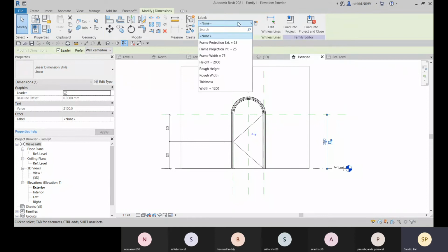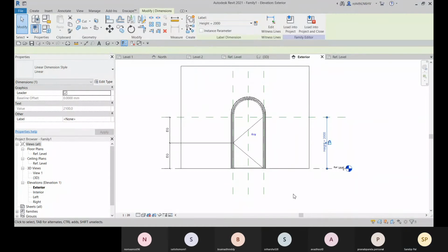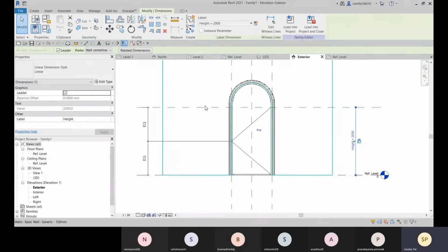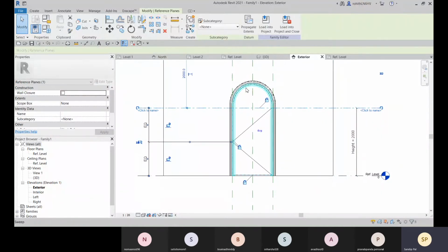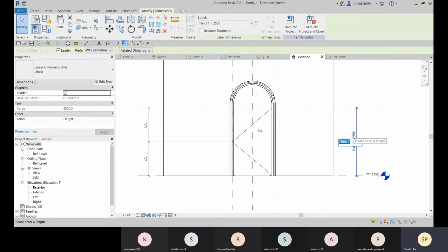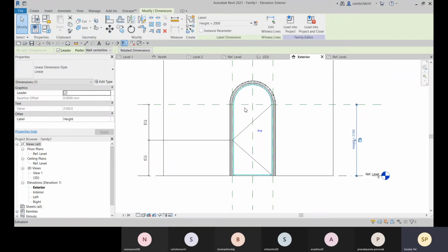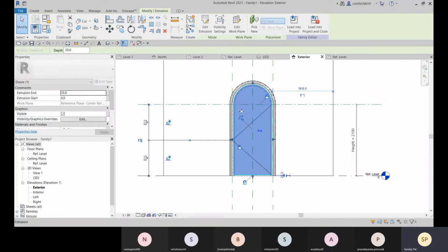So the height parameter, which is already created, you just select that height parameter. Okay. And now you can see that is changed. This height, this reference plane, which is changed. But these things are not changed, right? So we need to assign everything with this reference level. Okay. So from here we can apply changes for the values.